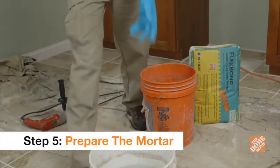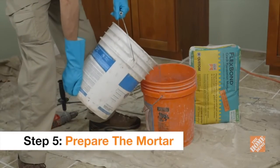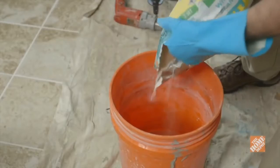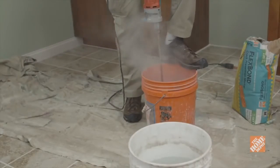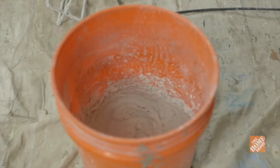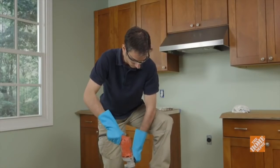To prepare powdered thin-set mortar for natural stone mosaic tile, fill your bucket with water as instructed by your manufacturer. Gradually add the thin-set powder, mixing it thoroughly. Let the mixture stand for 5 to 10 minutes. Then mix it again without adding additional water.